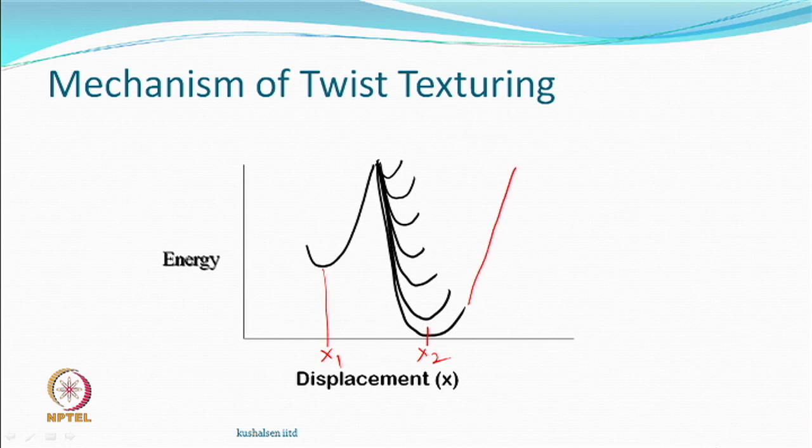When we do untwisting, the energy again goes up because you are doing it against the wish of the twisted multifilament yarn. Energy obviously would not like to remain at a higher state, would like to come down. So, if you remove the untwisting forces, what will happen? The yarn would like to go back, and the filaments within the yarn would like to go back to their original position, which they remember as the helical structure.